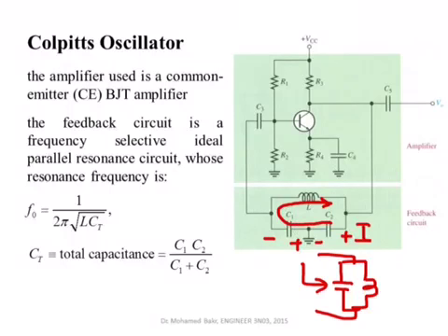So now we know the ratio between the feedback signal and the output signal. This is the ratio B we are looking for. Just remember that the ratio B I'm going to be using is the voltage VF over V out, what I'm feeding back over my output.